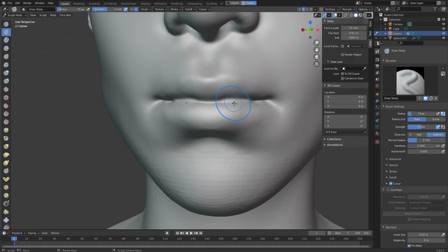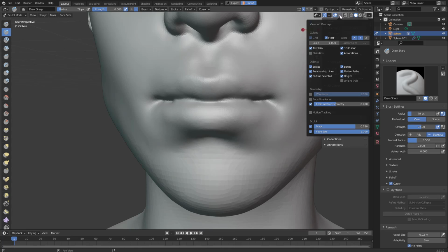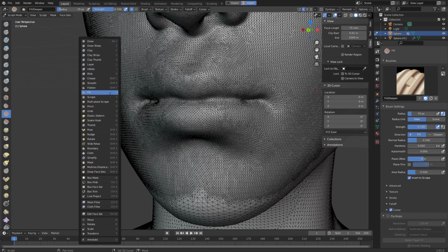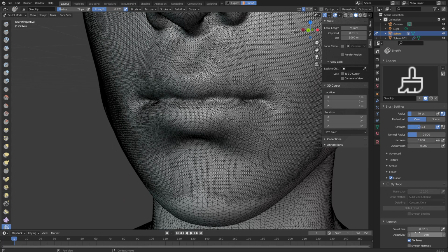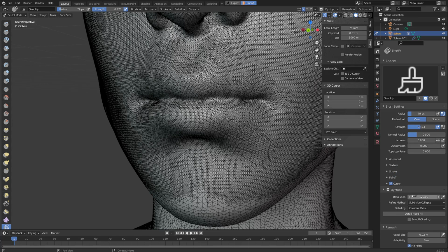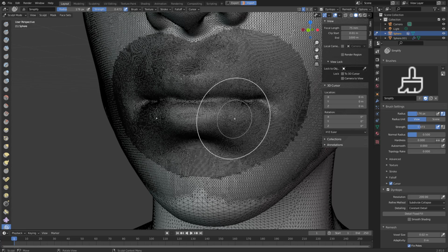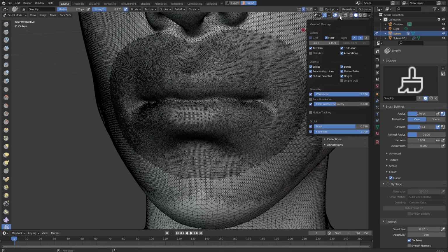So what I'm trying to do here is to toggle on wireframe, right? And then I'm gonna go to this Simplified Brush, and then here for Dyna Topo, toggle that on, and then 120 I'm gonna make higher, maybe 200, to give it even more resolution. Okay, and then toggle that off. Okay, now I should be able to create more detail in there.